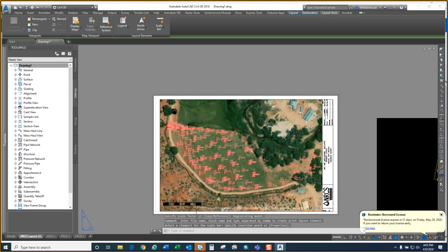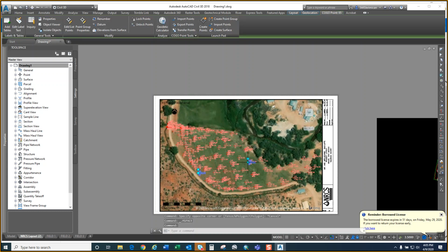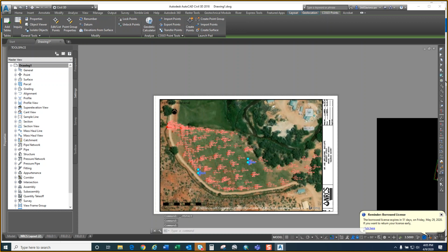So now you have a layout that's usable for measuring things, and you can know what the distance is from here. Double click into the viewport, make it into model space. If you want to know what the distance is from this point to this point, well, you now have a scale, and that looks about 320 feet using the scale.